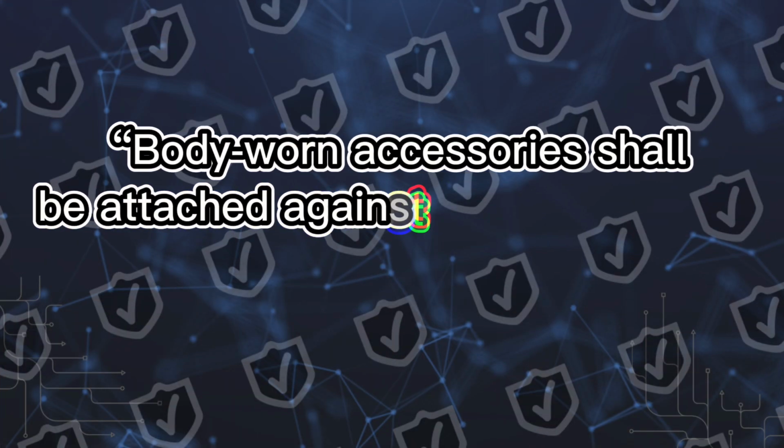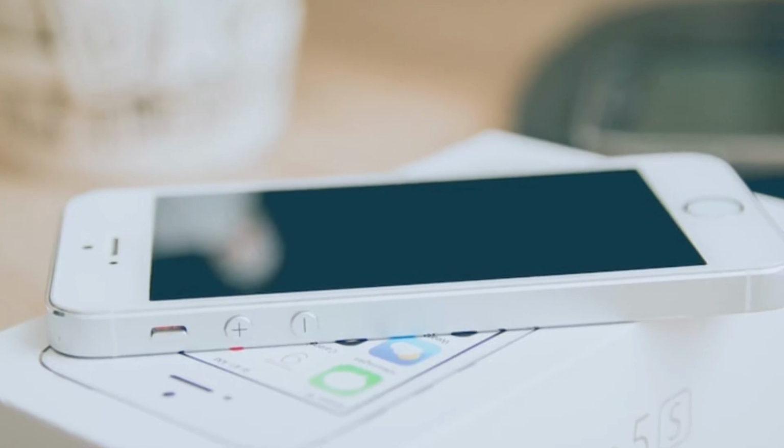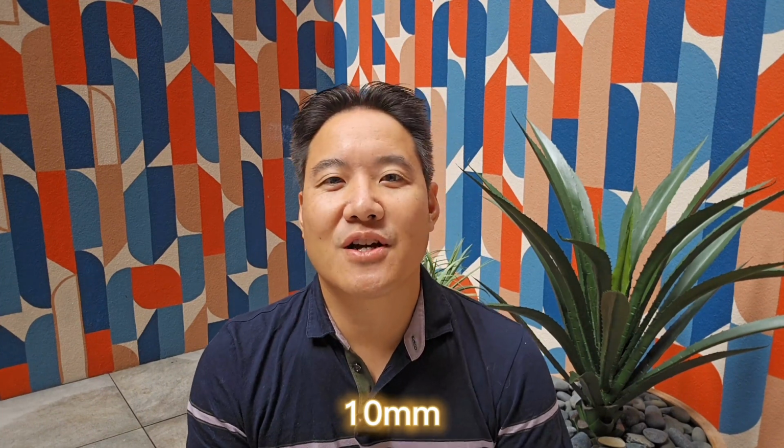So now, what exactly does body-worn mean today? The new RSS-102 issue 6, section 5.4 is going to say body-worn accessories shall be attached against the flat phantom in normal use conditions. And issue 6 goes on to explain requirements if your product supplies body-worn accessories in the box you get from the store or not. And lastly, if accessories aren't provided in the box, then a separation distance no farther than 10 millimeters is needed to be tested for SAR.